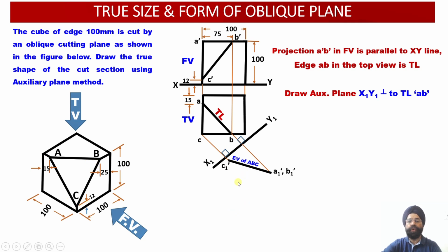Now I need to go parallel to this. So another auxiliary plane; this was AVP. Now I am going to draw AIP, because any plane which is drawn parallel to the elevation points will be AIP. Now this is the auxiliary front view which I had drawn.